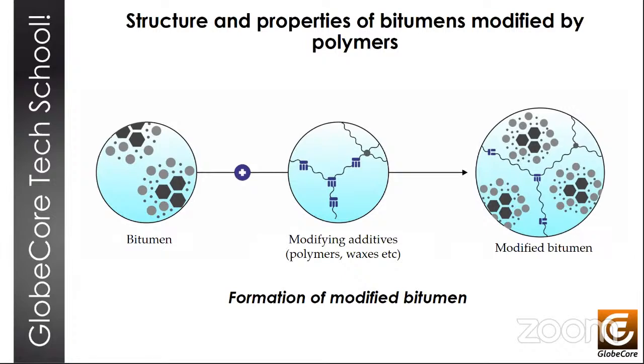This matrix then turns into a medium that transfers the physical load to the fibers. And in the event of fibers breaking, it quickly redistributes all these tensions and stresses. Such compositions are characterized by increased strength, elasticity, and resistance to fatigue fracture, which is especially necessary if we want to ensure the operational reliability and strength of the material.